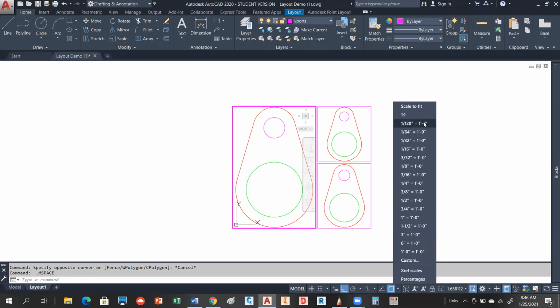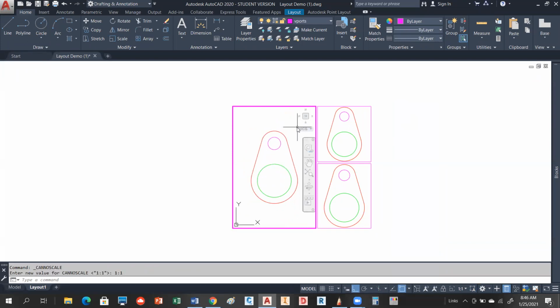So what we're going to do here is create the scale factor 1:1 XP. So we're going to go 1:1 right there. You should notice that this changes size within the viewport. So that actually is 1:1 on my paper right now. Did everybody get that to work that's trying this with me? So you have to be in the viewport and you have to set it. And notice if this one is set properly, it'll tell you down here that it's 1:1. Any questions?